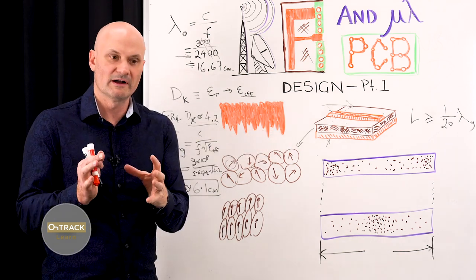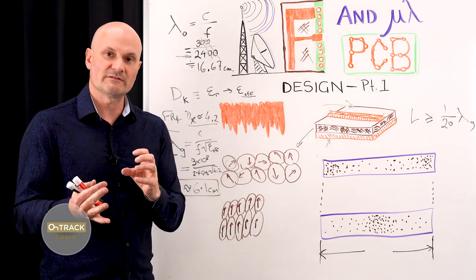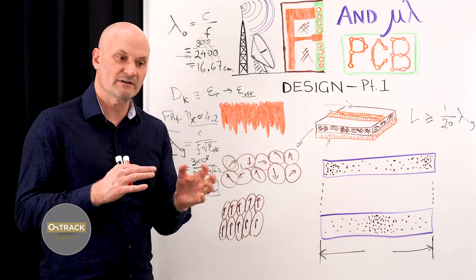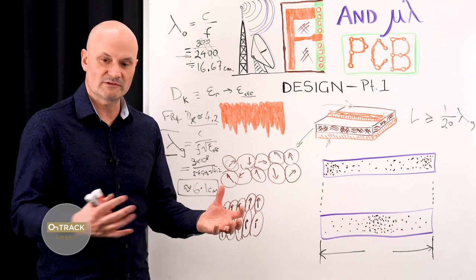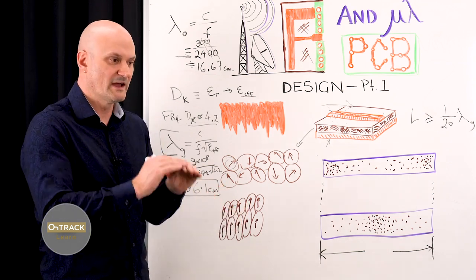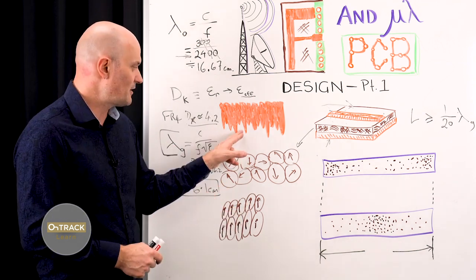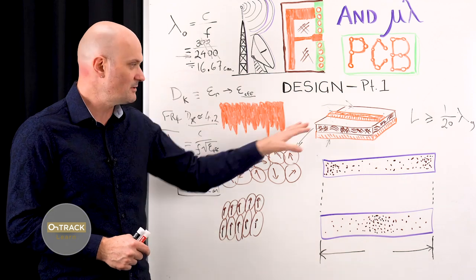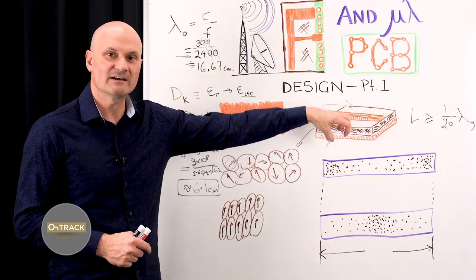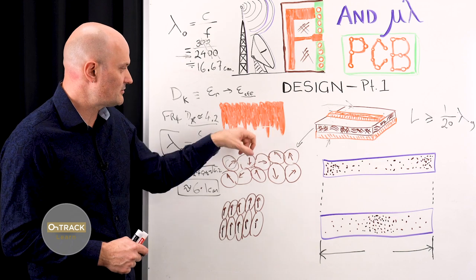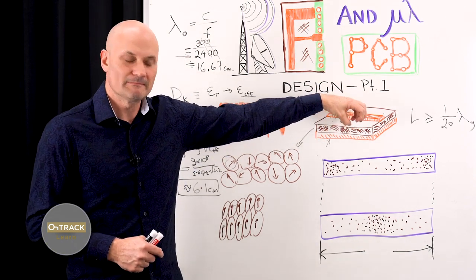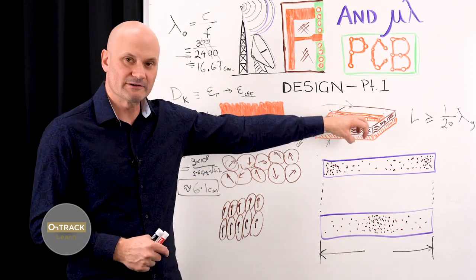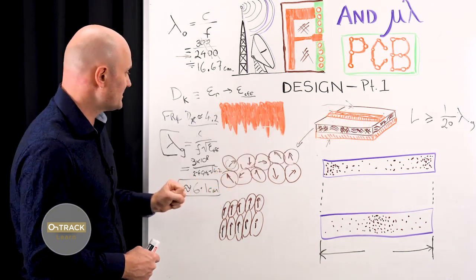They take the copper and it comes off a drum, and one side of it's smooth and the other side is rough. It's called electrodeposited copper because of the plating bath that's used to get copper out of solution onto a drum. And they make the foil out of that, and they want it rough on at least one side because that helps it adhere. This tooth, this is called the tooth, and that helps it adhere, like grab into the insulation material during the lamination cycles.